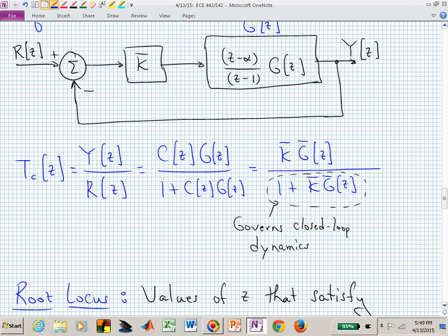So a PI controller is not a cure-all, but a PID controller does allow you to control a lot of different systems. If you're not happy with the transient that you're getting with a PI, sometimes you can introduce the derivative term to enhance your transient to what you need, and so a PID controller may be sufficient. And that covers a lot of the control systems in the world, the PID controller. So knowing that and being able to adjust that effectively is a good piece of knowledge to have.